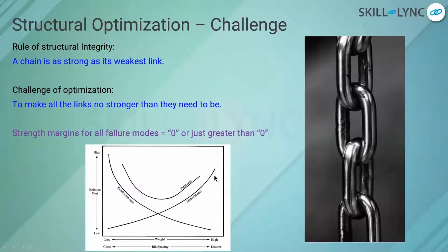But if I were to make a very efficient product, as we have seen in the lug case earlier, the amount of material that I need is less, but the fabrication cost is going to be very high. So again, I don't want to end up on this spectrum. There is a balance between the material cost and the fabrication cost, and hence the total cost.